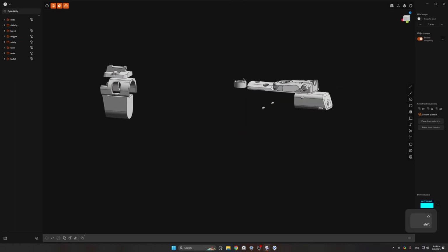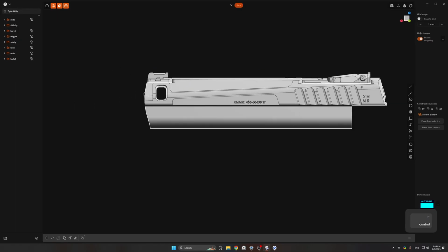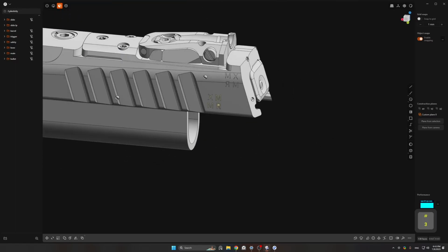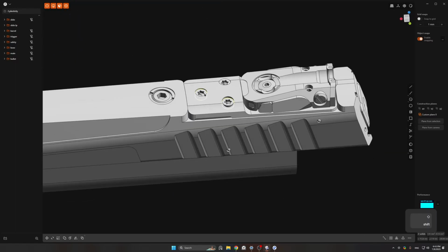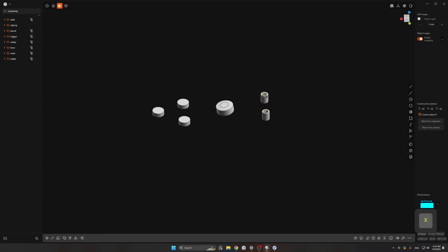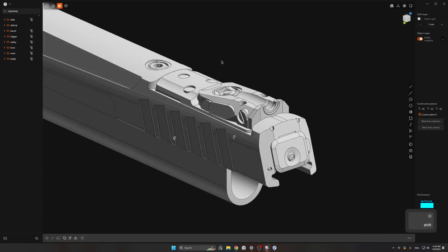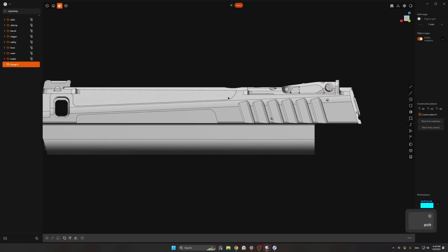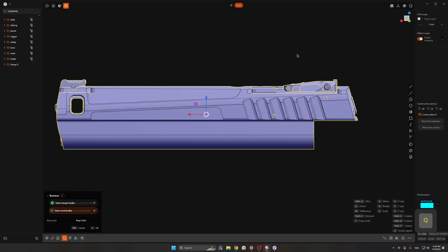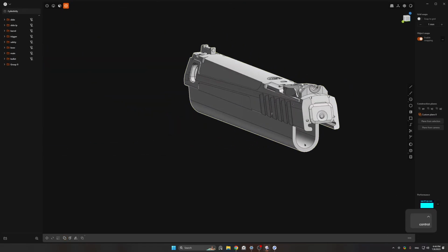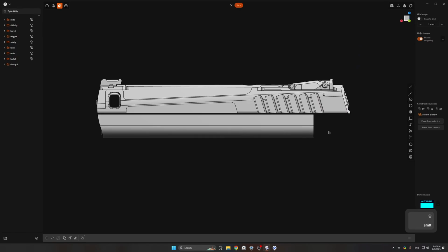So let's quickly do all the low poly things like deleting the text, deleting all the small insides of bolts here. And let's duplicate it again. It's gonna be our union boolean sheet. Let's now delete any face that we don't need to turn it into a sheet body.